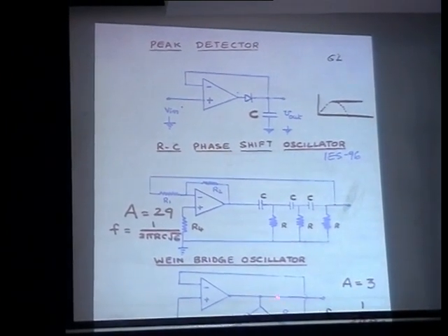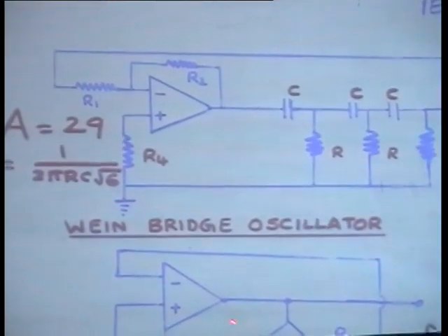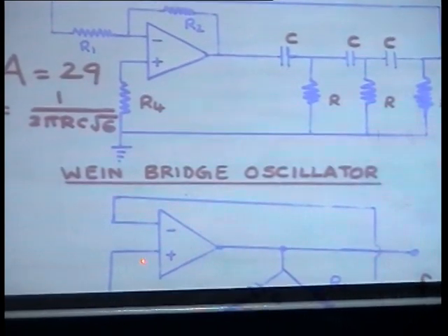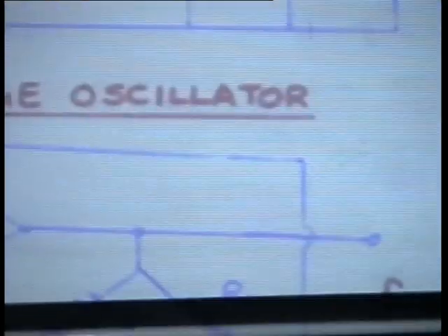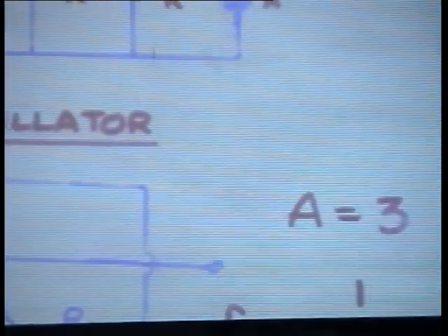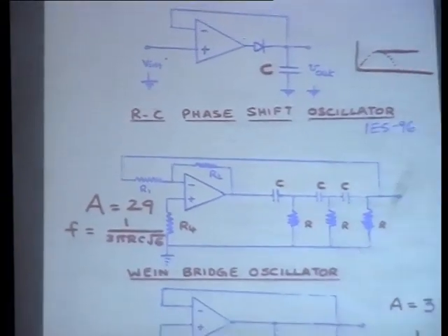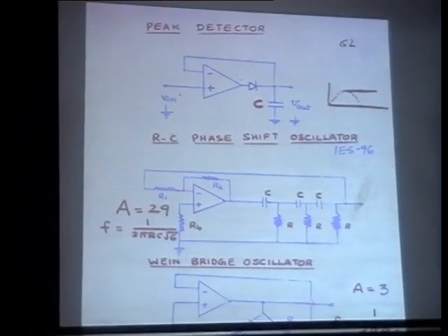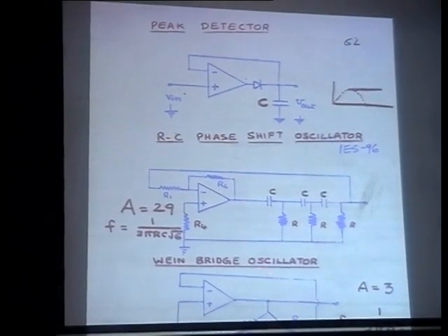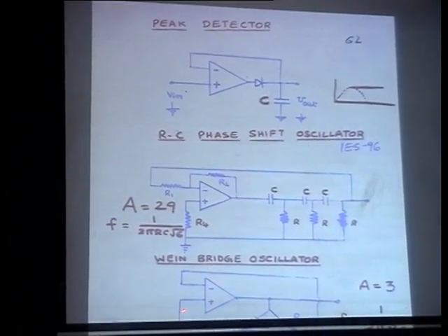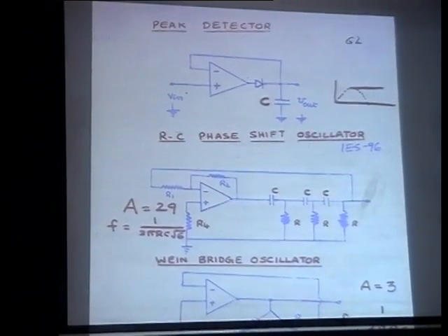Next you have the Wien bridge oscillator. In the Wien bridge oscillator you have that RC section and you have your op-amp. You are giving both positive feedback and negative feedback, but positive feedback will be made higher than the negative feedback. Ultimately oscillator is a positive feedback amplifier. So I have a Wien bridge, and that is Wien bridge oscillator.